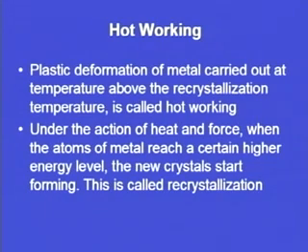Let me summarize once again. Under the action of heat and force, whenever the atoms of the metal reach a certain higher energy level, new crystals start to form, and this is called recrystallization, and the temperature at which this happens is called the recrystallization temperature. Whenever we are working above this temperature, it will be categorized as hot working. Whenever we are working below this temperature, it will be categorized as cold working.